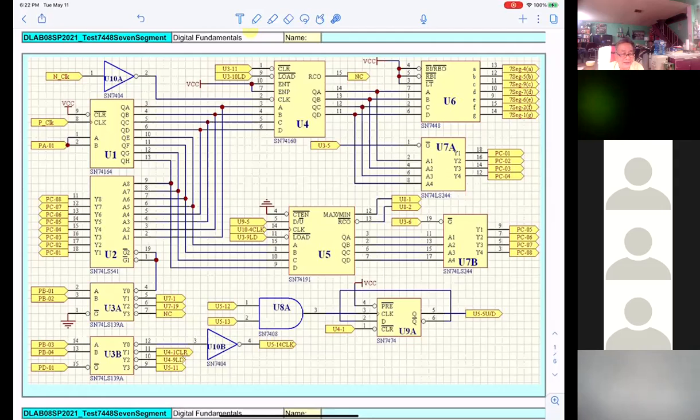And pin 19 controls the second 4 bits. That's easy for the people when they design the circuitry. Sometimes they want only a 4 bit buffer. Then they can use 244. But they cannot use 541. 541 is 8 bits at a time.